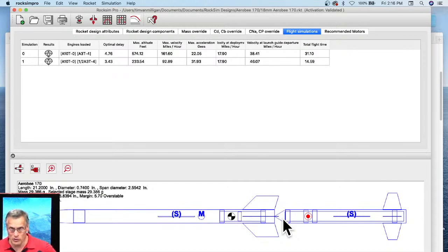You pick your rocket motor based on your rocket and your flying field, because you don't want to pick a rocket motor that's going to fly off of your field, because then you're going to lose your rocket. If you lose the rocket, you also lose that expensive casing in the back end. So when you pick a motor, it doesn't really matter if it's single use or reloadable. Always start with picking a rocket motor that will give you a good flight. And then from that point, we go back to the Apogee website and find that particular motor.